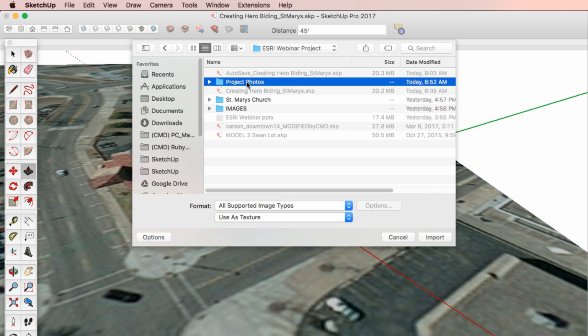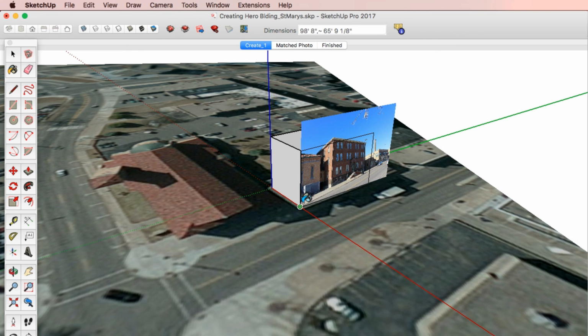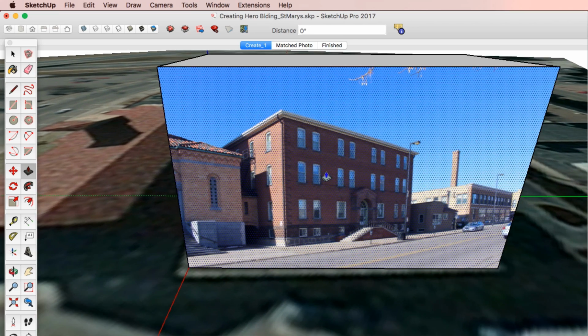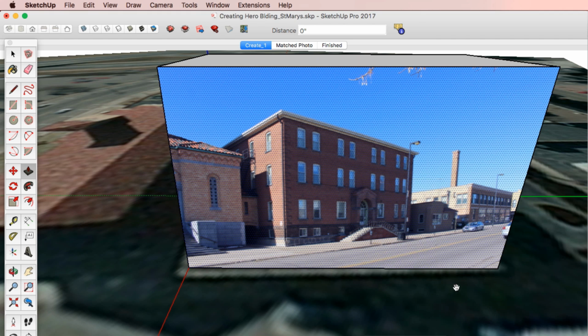So it has multiple windows and doors and so forth, but instead of just drawing every single door, I'm actually going to use a photograph taken by a camera and bring it right into the SketchUp environment as a texture. And I'm just going to apply it straight onto the front surface. I didn't edit the photograph in any way. And you notice that obviously it's not fitting that front facade very well.